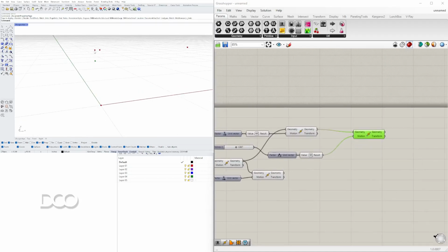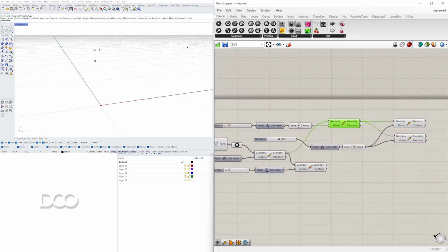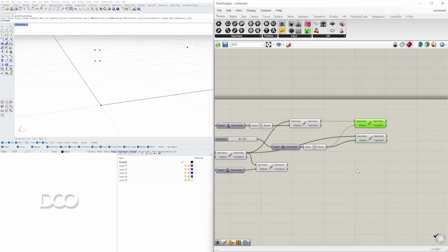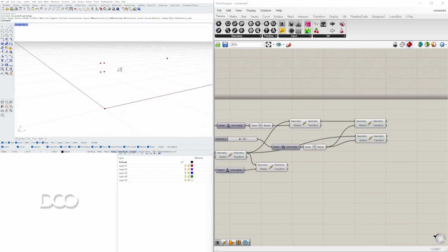and not only do we need to bring down this point, we also need to bring down this point. So I'll take this, and we want each point to be its own separate output. So I'll copy this down, holding down Alt, and then bring over geometry from this one. We have all of these as a separate output. This way, now all we need to do is connect the points here. So depending on if we want a fillet edge or a rounded edge here or down here, those details would also be worked out before we create that entire array.